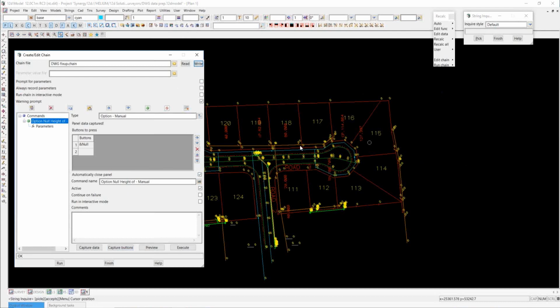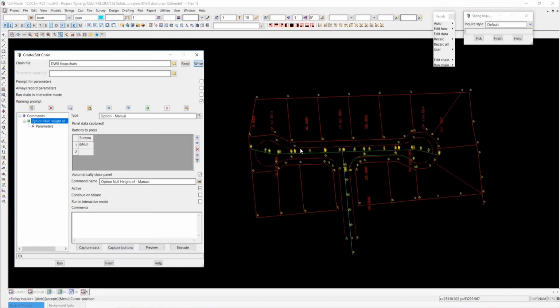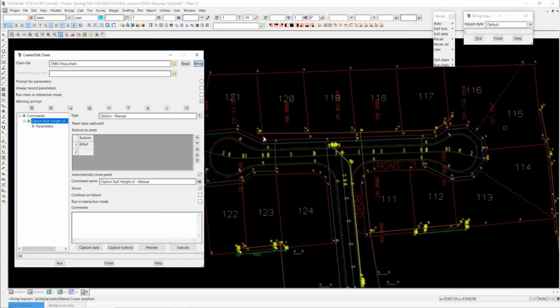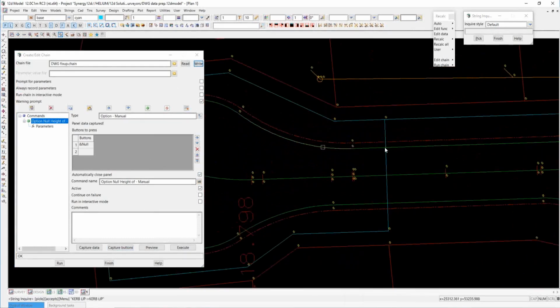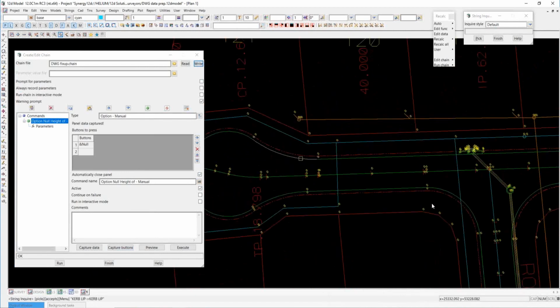So if I write that away, the next thing I want to do is join all of these strings to each other, so it's one nice long string around the lip of curve, back of curve, and the boundary strings.